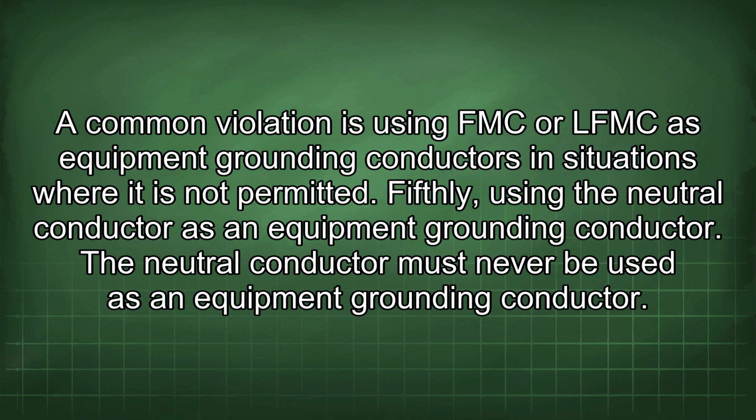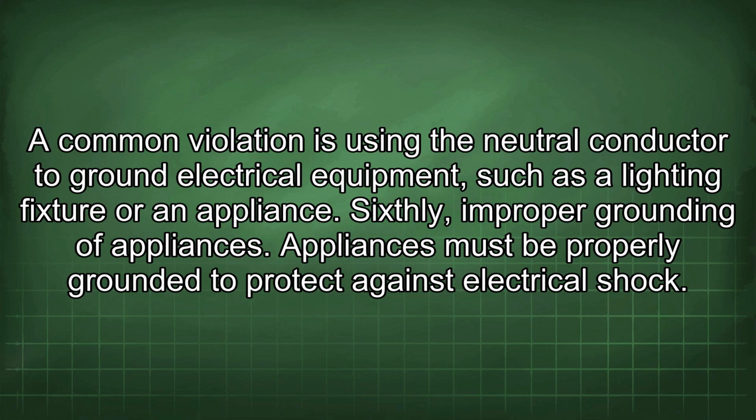Fifthly, using the neutral conductor as an equipment grounding conductor. The neutral conductor must never be used as an equipment grounding conductor. A common violation is using the neutral conductor to ground electrical equipment, such as a lighting fixture or an appliance.